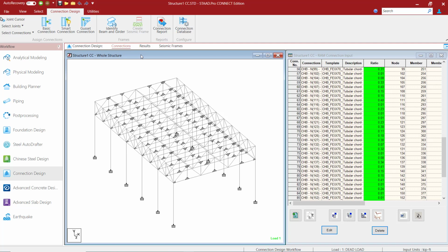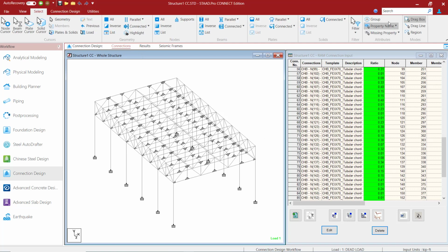Now, let's go ahead and work on our side trusses, okay? Now the side trusses have non-HSS sections in them. You know, my chord sections are wide flange, some of my branches are channels, some of my branches are steel rods. So I know what that does for me is it basically pushes me into an area where they're still acting like a truss, but I need to go ahead and assign a gusset truss connection to those joints. So let's go ahead and make that selection.